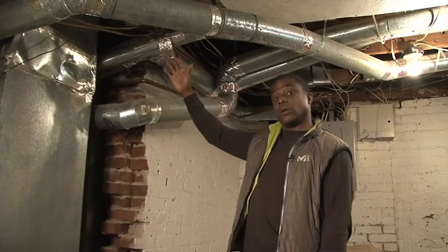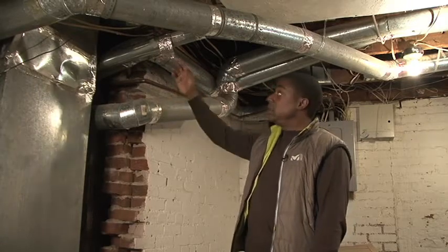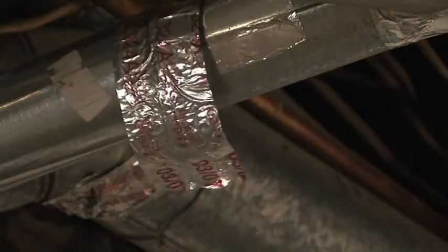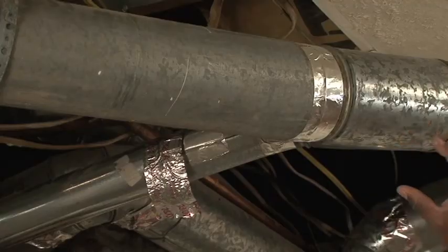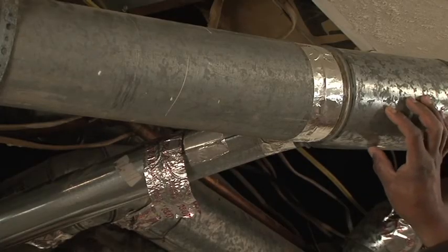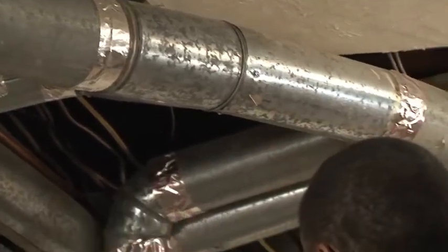We also notice on our flue pipe for our water heater and our furnace, we have this metallized tape. And we shouldn't have metallized tape or duct tape or mastic anywhere on our flue pipe. And after this Y, we should have double-walled B-vent going all the way out of the house, all the way up to the spark arrestor outside the house.